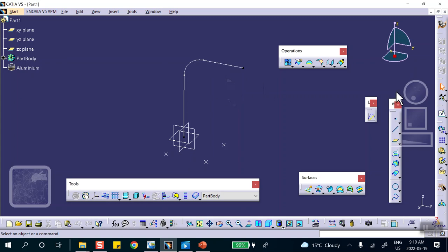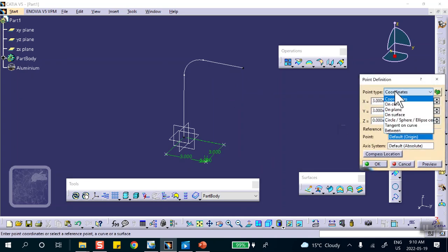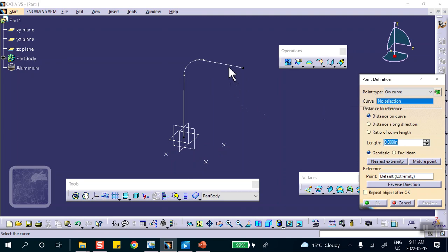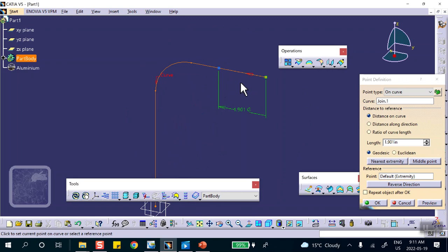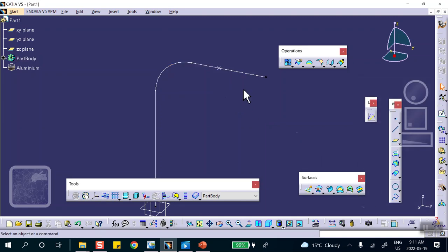And the way to do it, you go create a point, not with coordinates, on a curve. That's easier for me. It says where on this curve. Okay, is that good? See that blue dot there? A point on a curve. I picked the curve, and I can type the coordinates now, or I can drag it until where I want. So we say, okay, that's good, perfect. So a point has been created on that curve.